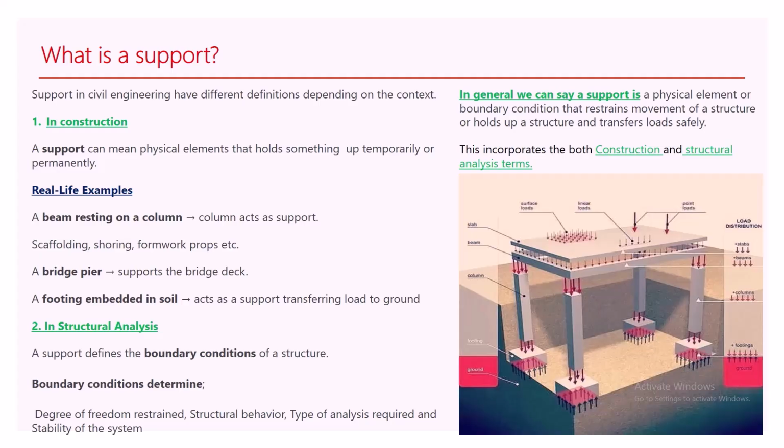So another type of support we can have is in structural analysis. In structural analysis, you have a different definition, and it is defined that a support defines the boundary condition of a structure. That is deep. So what does it actually define? You see that your support defines or determines the degree of freedom, that is, how restrained your structure is.